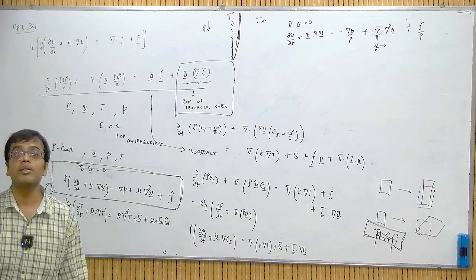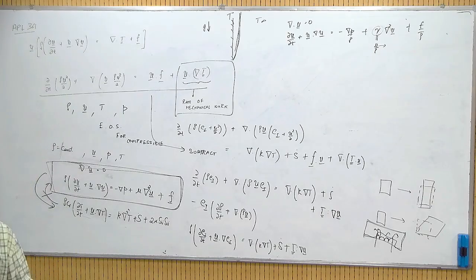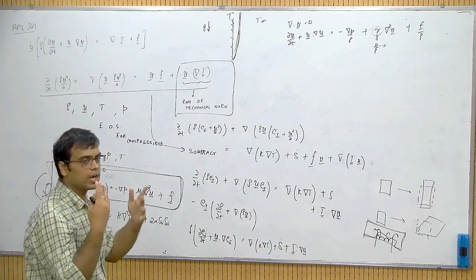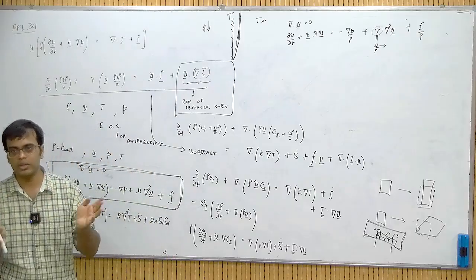For example, we all think that honey is denser than water. Is honey denser, more viscous than water, or both? The answer to that question you will find if you can quantify what is rho and nu separately. You have to account for nu and rho separately to answer these questions. Intuitively, it's very hard to separate the two.